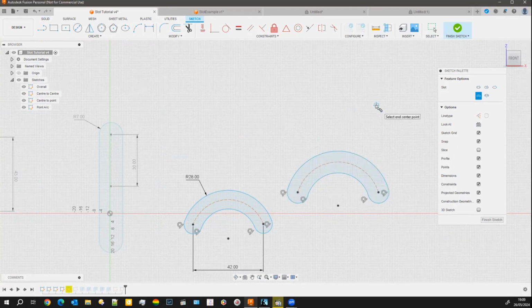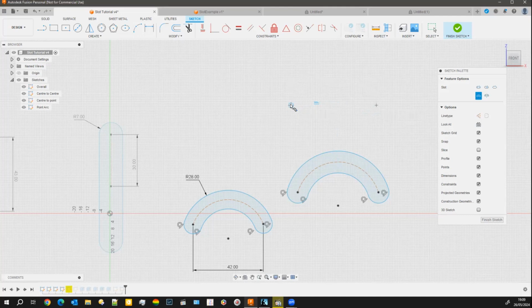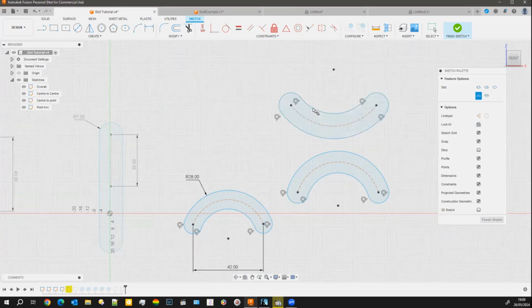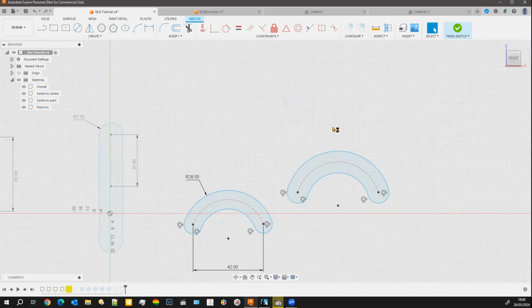So that's the 1 point. The second point that you can put a size on, type in the size if you want to. Left mouse button, and then drag up to the arc that you want. And then find where you want it. Left click it to set it, and then the width of it. And that's the 3-point arc. Let me just clear the area.